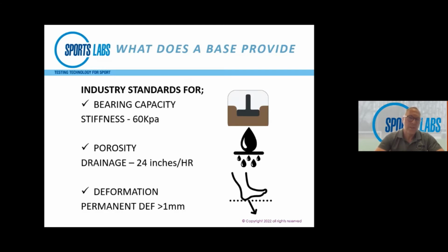So we've set a standard for ourselves. If we were designers and we went out to check a base, we would be looking for the majority of the subbase platform to hit that standard. Generally speaking, if you do hit soft spots, they can be fairly easily remediated whilst you're on site, whilst you're doing the testing, and that's a scenario we encourage.